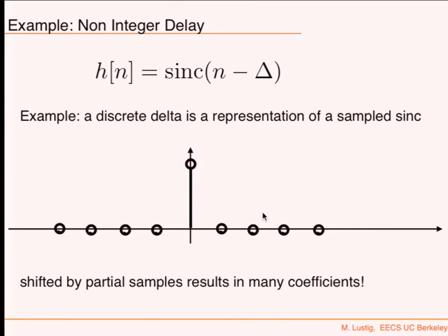When we sample, we assume that our signal is band-limited. If we're thinking about a perfect reconstruction in continuous time, it's always band-limited. I can't really sample a Dirac function. It's not band-limited. A continuous Dirac function I cannot sample and be able to represent it.